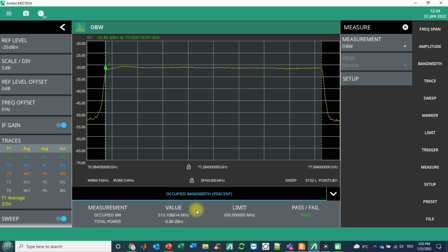So easy was it to measure, first of all, in the time domain, the chirp time frame and the frame periodicity, and the latter figure is essential to get a stable readout later on for the channel power measurement.